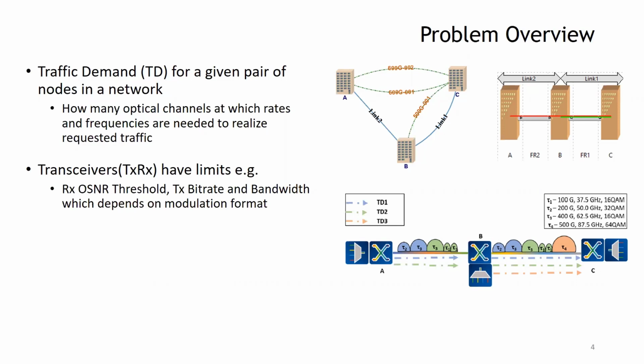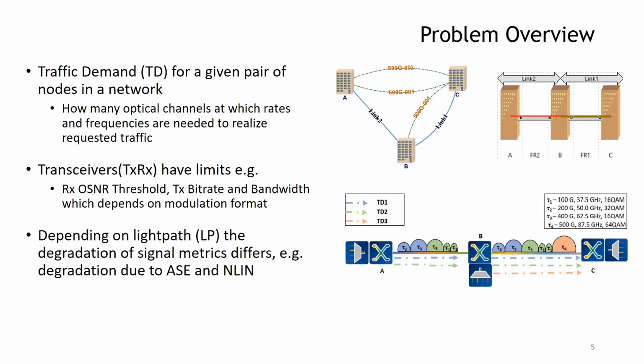Selecting transceiver configuration with respect to quality of service, we define the bandwidth of a light path, in other words, spectrum utilization. Having multiple traffic demands in a network, intuitively we should allocate light paths as close to each other as possible. At this moment, the nonlinear interactions of light paths or optical channels within the fiber come into play. And one more difficulty appears.